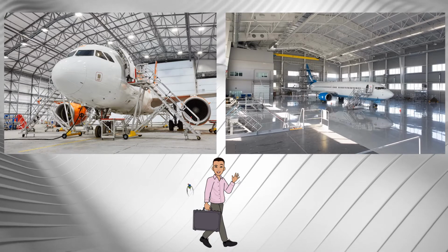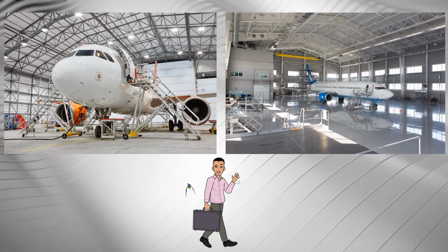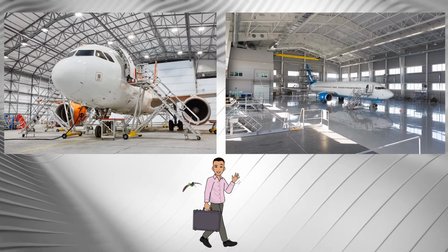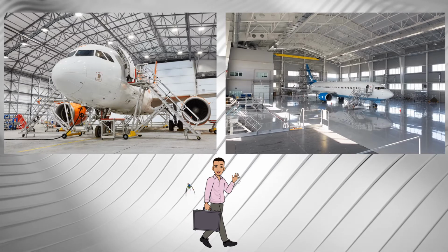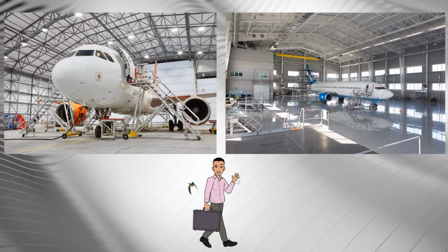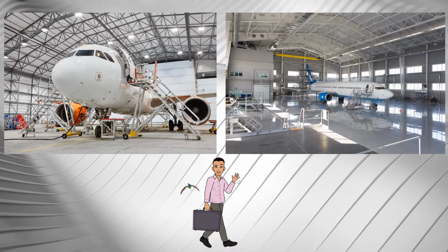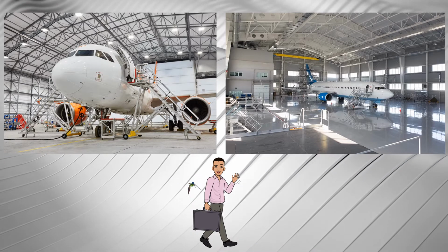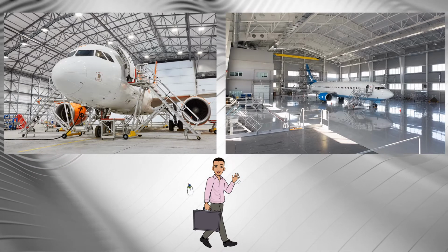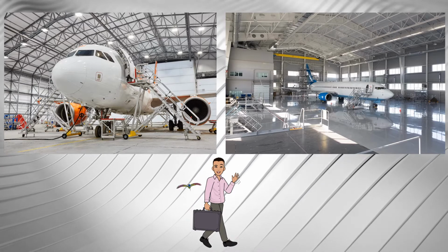Unless they can be moved out of the hangar, docks occupy a large amount of floor space. They obstruct the placing and maintenance of other types of aircraft when not in use. Consequently, tail docks and body docks are sometimes suspended from the hangar roof. Since tail docks weigh 12 to 50 tons and body docks 50 to 100 tons, provision for them must be incorporated in the roof design.